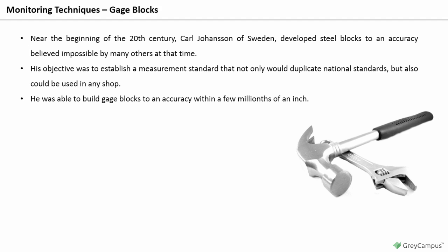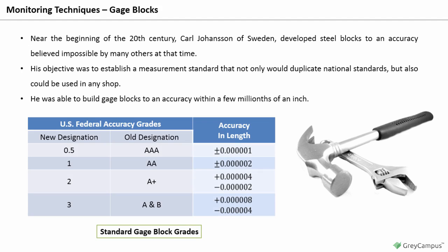Block stacks are assembled by a ringing process which attaches the blocks by a combination of molecular attraction and the adhesive effect of a very thin oil film. Air between the block boundaries is squeezed out. The sequential steps for the ringing of rectangular blocks is shown below. Light pressure is used throughout the process.